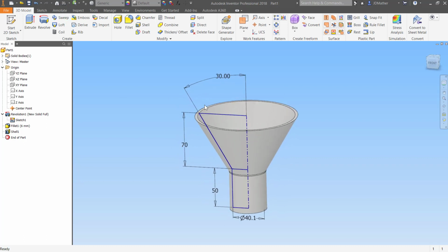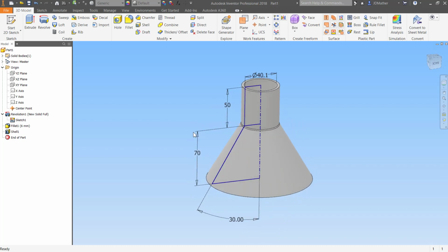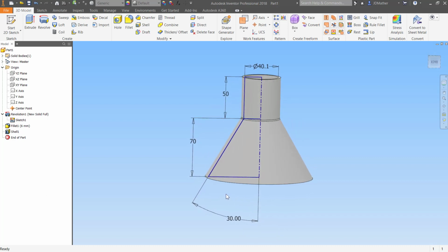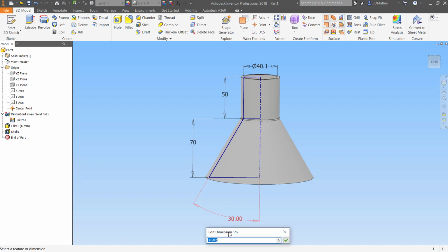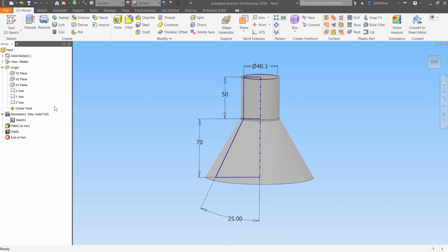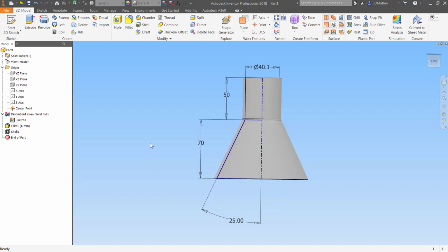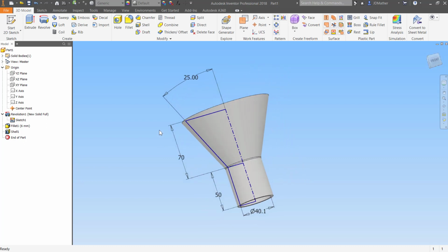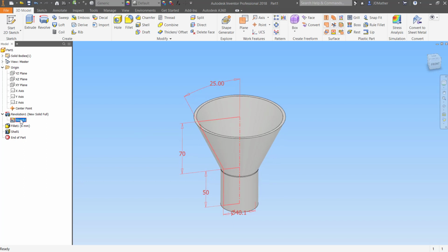Now on the angle, if you're going to 3D print this, say this is the bed of your printer, if the angle is too great, your printer will have to build support structure. But if it isn't too great, it may not need to build a support structure. So that is dependent on your particular printer. So you need to keep in mind those design ideas, design for manufacturability, how you want to print this. Let's right click and turn off the visibility of that sketch.